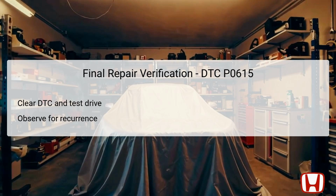This process begins by clearing the DTC from the PCM using a diagnostic tool, followed by conducting a test drive. During the test drive, the technician should monitor the vehicle's performance closely to check for any signs of malfunction. If the vehicle starts without issues and no warning lights reappear, it indicates that the repair has been successful.